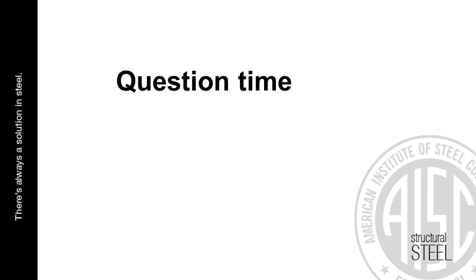This is another thing that I've discussed with the bender rollers. Sometimes you can cold bend it and dip it, and everything works out perfectly. You don't have to worry about anything. Sometimes you cold bend it, dip it, and the radius changes. So you have to go back to the bender roller and run it back through. If they did pyramid roll bending, running it back through the machine tends to damage the galvanizing. So do you want to send it back to the galvanizer, or what do you do about that? It's really a question that, once again, I don't have a good answer for you.